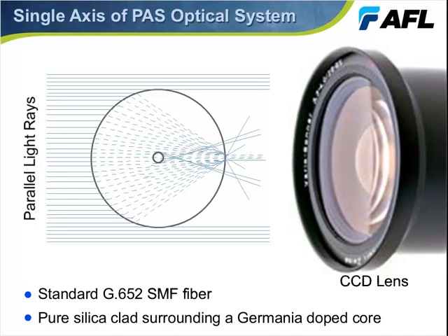When you look into the pond, things under the water are not exactly where you think they are because the light is bending. And the same thing is happening here. And the amount that the light bends is due to the difference in the index of refraction between air and glass and also the incident angle. So that's why the light rays that hit towards the outside of the fiber bend inwards more than the ones that are close to the center. And that's why the light is all kind of fanning inwards towards the center of the fiber.